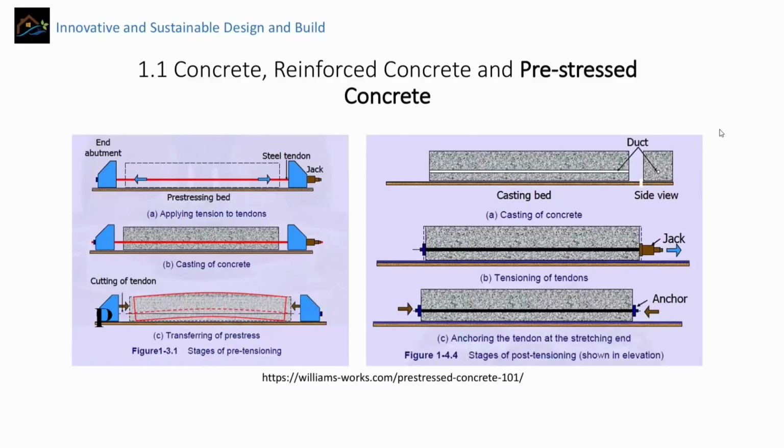The way the pre-stressed concrete works is that first we make the forms and the molds, and then we add those high strength steel bars fixed at the end, and then we add the concrete, knowing that these steel bars are stressed and in tension, and then this tension in these steel bars comes into equilibrium after the concrete gets hardened.